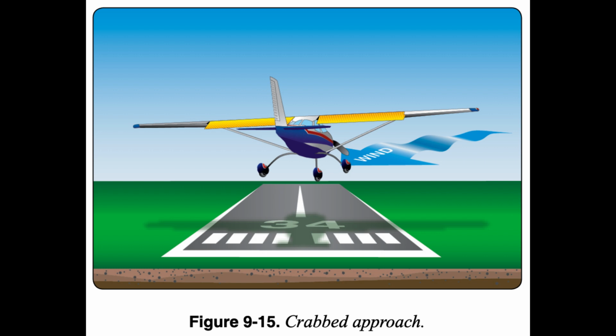End of page 9-15. While the wing-low, side-slip method also compensates for a crosswind from any angle, it keeps the airplane's ground track and longitudinal axis aligned with the runway centerline throughout the final approach, round out, touchdown, and after-landing roll. This prevents the airplane from touching down in a sideward motion and imposing damaging side loads on the landing gear. When first experienced, it may seem odd to land while holding a bank angle.